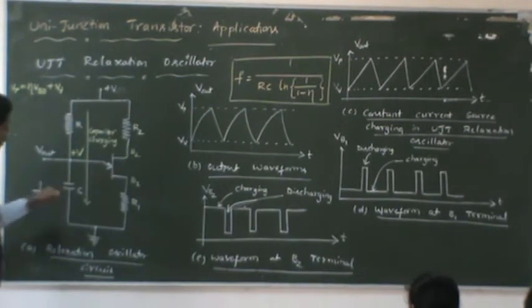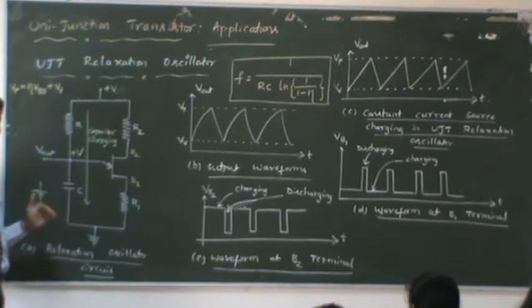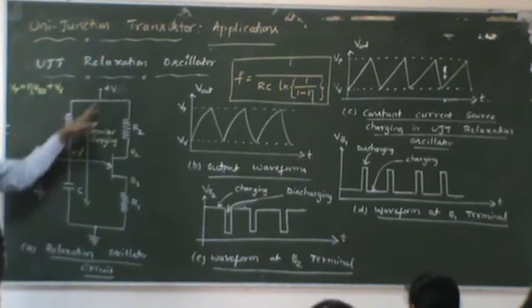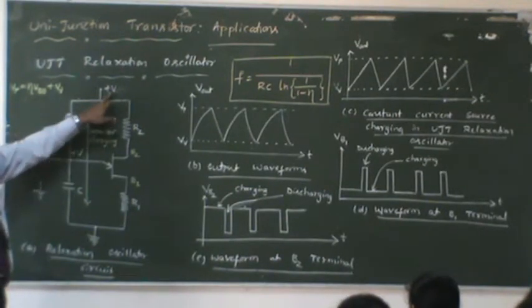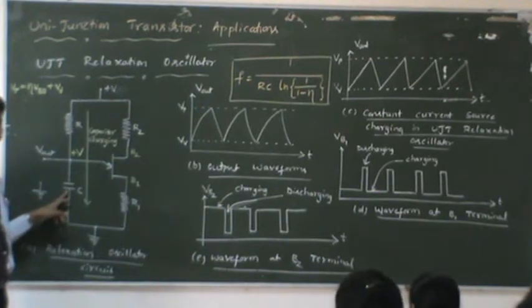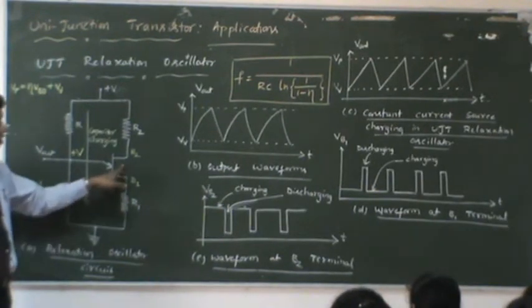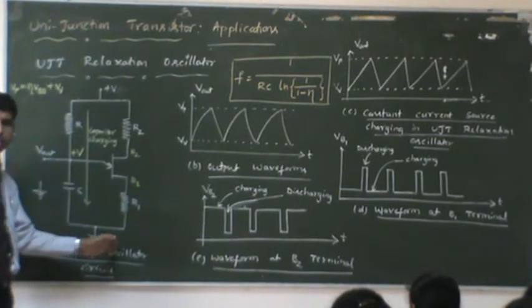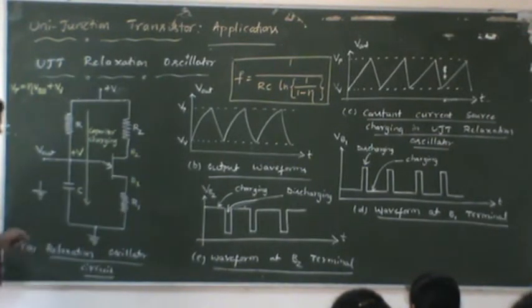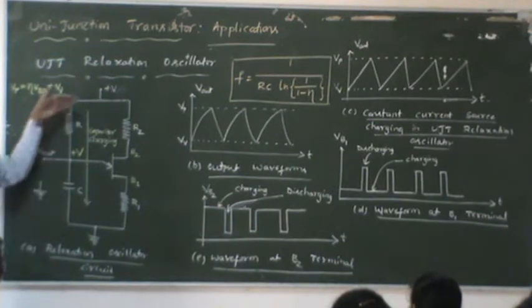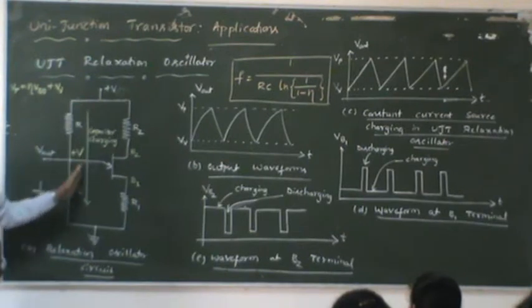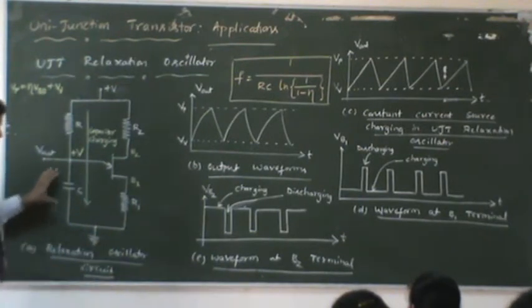Now here we have taken a condition from reverse bias to forward bias. Initially we switch on this power supply. This capacitor has no charge. When there is no charge in this, the diode present inside this is reverse biased. There was some leakage flowing in this part. But now let us assume the condition where the capacitor has been fully charged. Because you continuously keep giving supply, it has been completely charged through this path. Once the capacitor charges, it behaves like a source of the system.